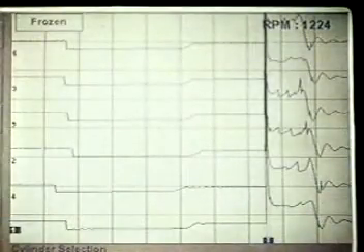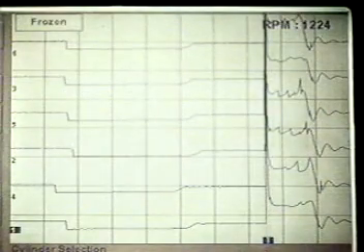So what we're going to do is the intake cleaning that we talked about, the injector cleaning, and of course R&R the secondary components. So we'll bring the car back in after we do these maintenance procedures and show you the improvement in the spark duration period, which would obviously improve the drivability of this vehicle.